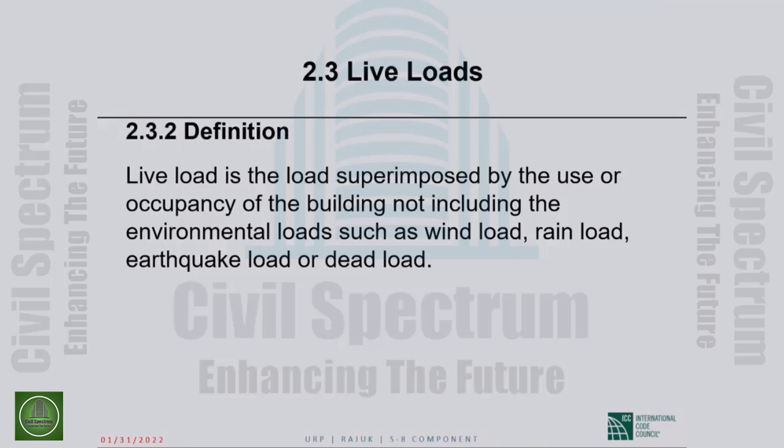Everything else, absolutely everything else, all the other loads are parasitic loads. Dead load is the first one. In order to impose live loads on our structure, we have to design to carry the weight of the structure, which is much more than the live loads, but we have no choice. Wind is a parasitic load that's always present. We have to do something about it. Otherwise our structure will be blown away. So that perspective is important. Live load is the reason why we erect our structure. Live load is the load.